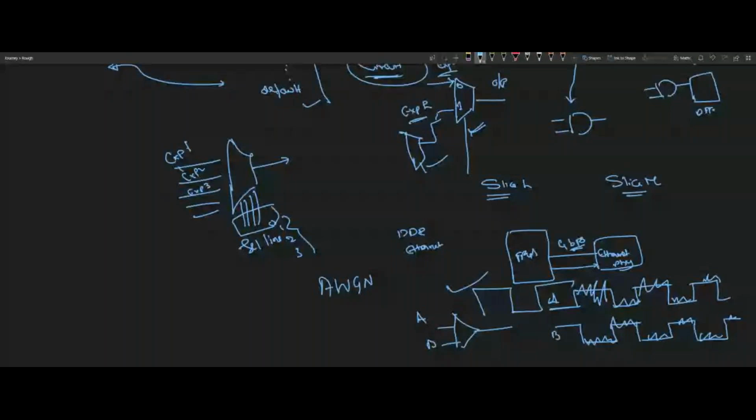Now you feel that whatever circuitry you have loaded, you don't want it to act like a full adder anymore. You want a ripple carry adder. So what do you do? You change the RTL, generate the bit file again, and program it into the FPGA. Now that FPGA will act like a ripple carry adder, correct? That's why we call it reprogrammable.